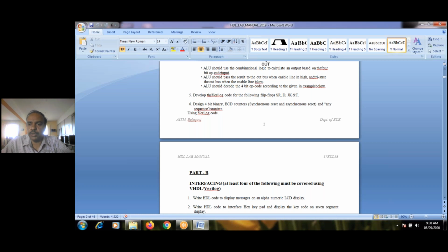That basically controls your working of decoder. So if enable is high, it won't check for any of the 3 inputs A, B or C. Irrespective of these 3 inputs, it will be giving you the output as what? All zeros. Correct, right? If enable is low or 0, next what it does? If enable is 0, then only it checks your input. If it is 000, I think D0 will be high, other bits they'll remain 0.